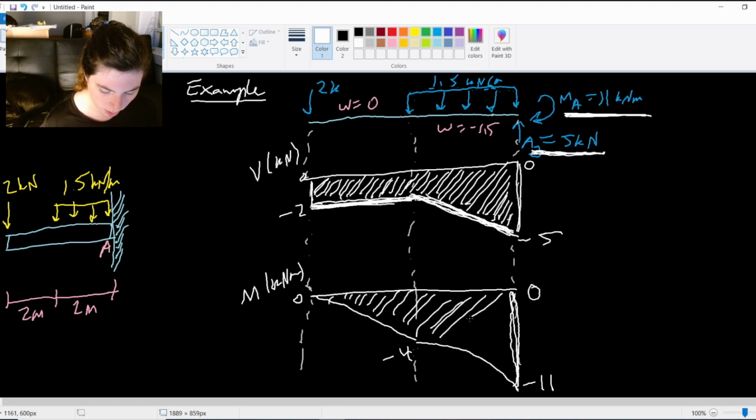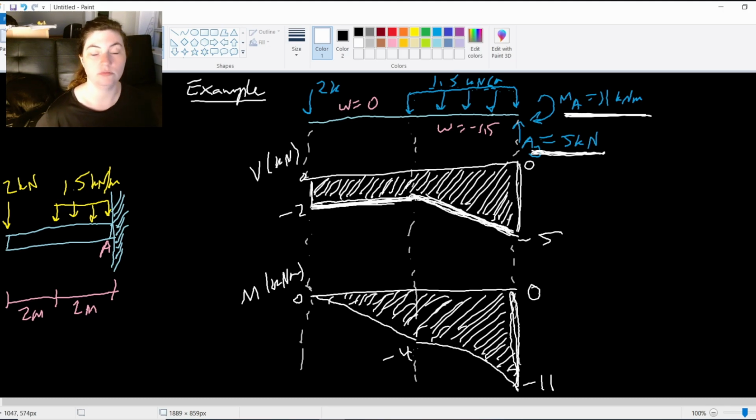Right, so it's not perfect. It's maybe not the exact 100% immaculate placement of my parabola, but you can see the general shape of it. You can see where the maximums are, where the greatest values are, and how this moment changes from linear to parabolic. It's clear that it is going through a change from a straight to a curved line. Those are the things that are really important.